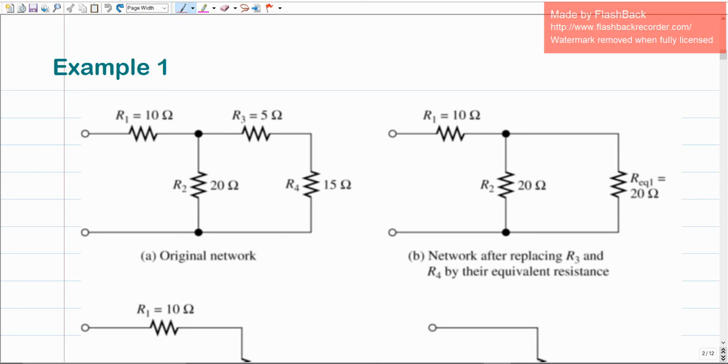The first step, in a way, is that you should distribute the current through the electrical circuit. So if we decide to start here, there should be some source here, right? Forget about the source for now. It means that there should be current I, which is the total current that comes from the source. This current is going to flow through the resistance R1. So if I ask you how much is the current over R1, you should understand that it is the total current, which is I. And then at this node, node number 1, this is node 1.